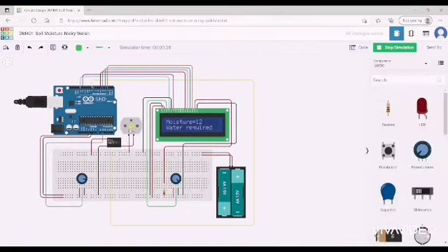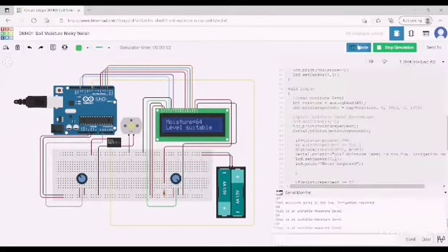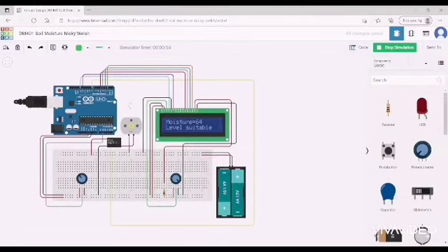Because of this, the DC motor is now running to put water into the soil. When the percentage is increased to 39 and now 64, because this is over 50, and between 50 and 67, it means the moisture level is suitable, and this is displayed again in the LCD monitor and the serial monitor. Also, because of this, the DC motor is turned off as water is no longer required.